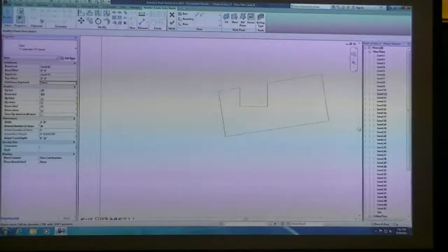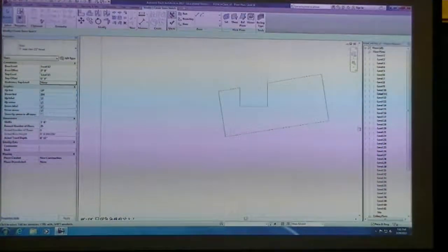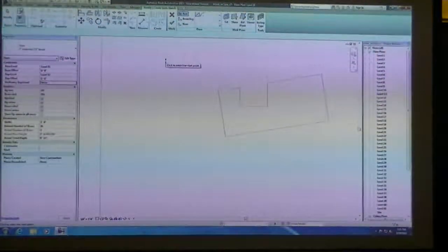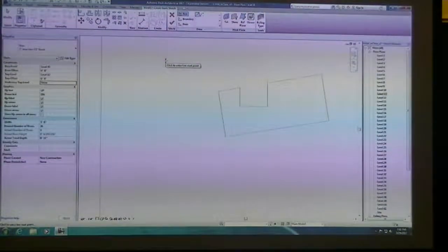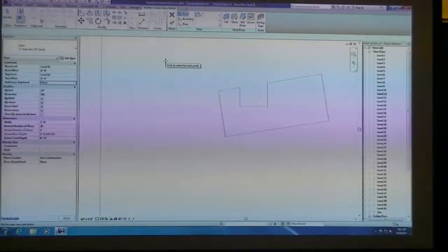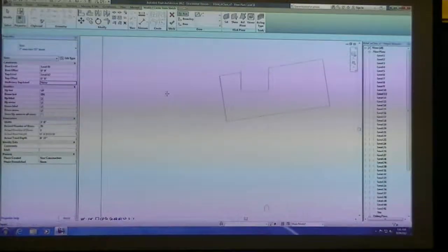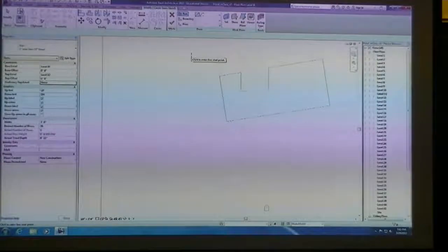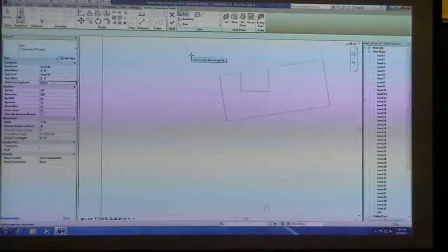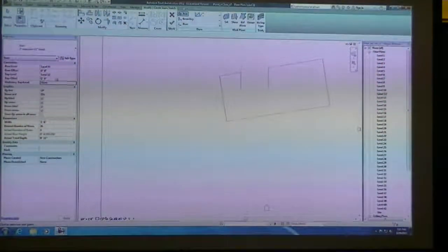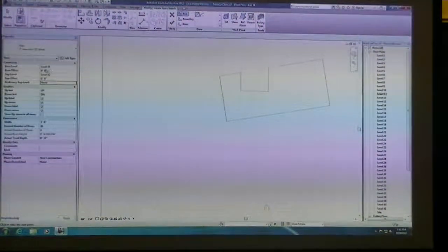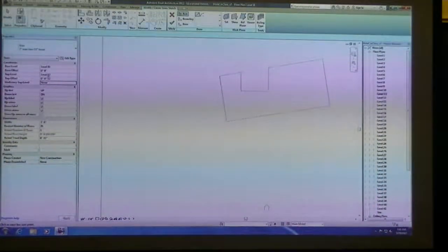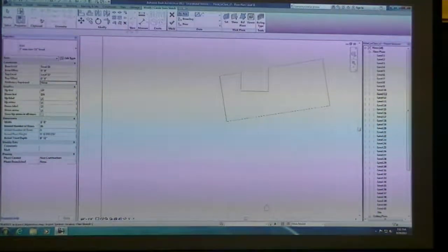Under Home, click under Stairs, and remember we did draw a stair a long time ago with the bridge and it didn't quite work out with our bridge. It'll work out a little bit better now that we're actually doing a building. Now that we have datum lines to go to from level 1 to level 2 or whatever the different levels are, if I'm on a particular level like level 11, my base level is set to level 11, and by default it assumes you want the stair to go up to the next level. So the top level is set to level 12 in my example.